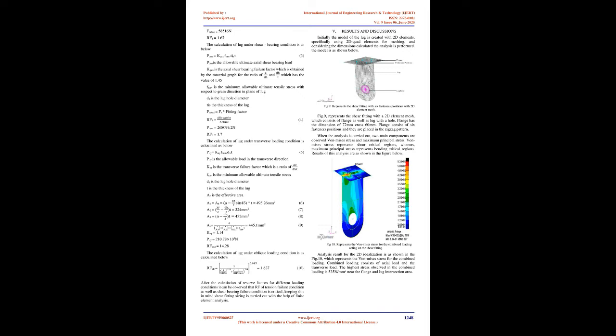Ultimate bearing strength in L, FBS, E/D equals 1.5, equals 94 KSI equals 649 N/mm2. Ultimate bearing strength in L, FBS, E/D equals 2, equals 115 KSI equals 794 N/mm2. Factor of safety equals 1.5.